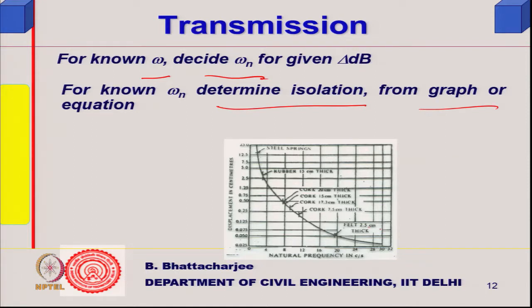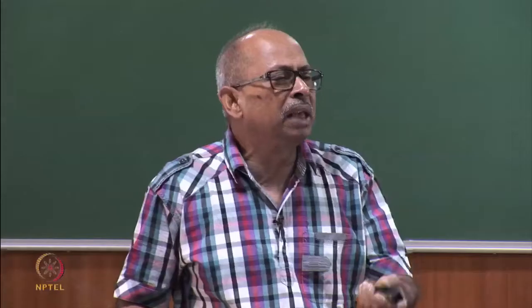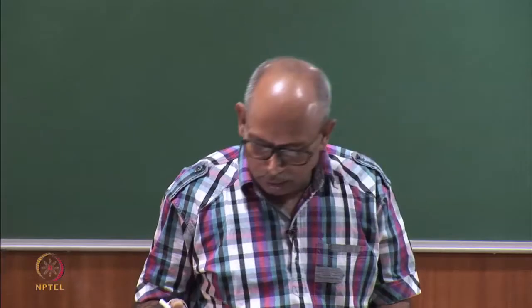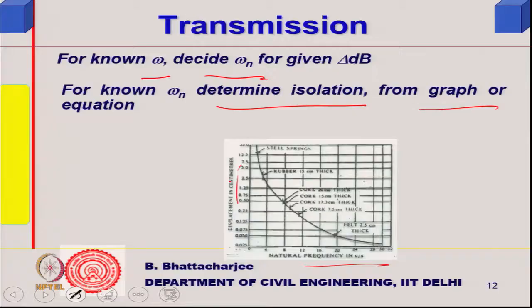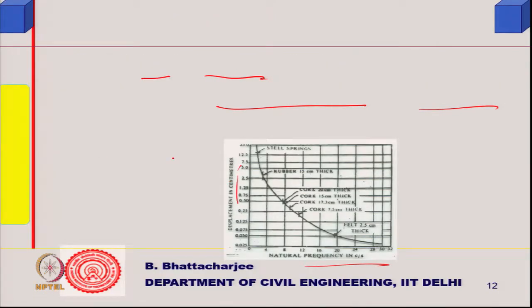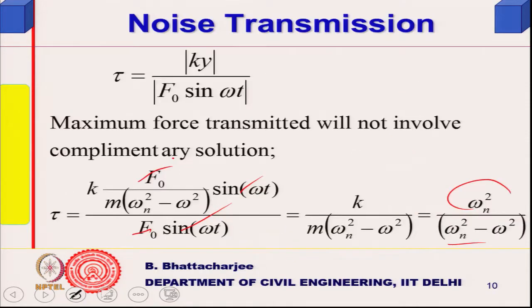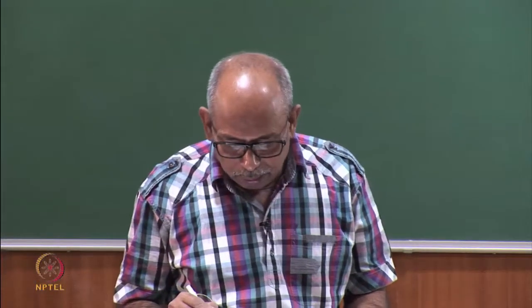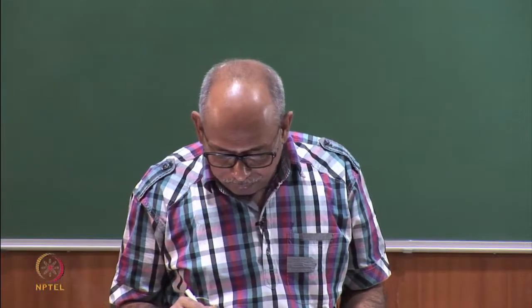You see, this graph gives us, for example, natural frequency versus static displacement, or simply 15.76 under root 1 by delta, the formula that I gave you earlier. One can determine from this, remember this formula we talked about, which is given in the National Building Code. You need not look into the code, but look at the material, and for the given load.